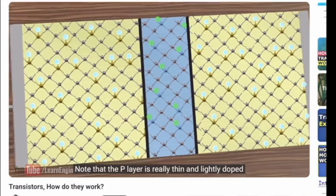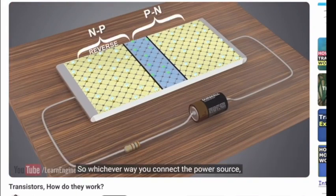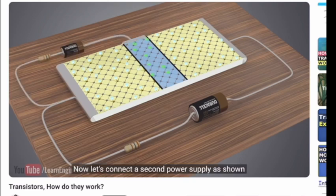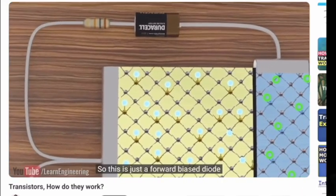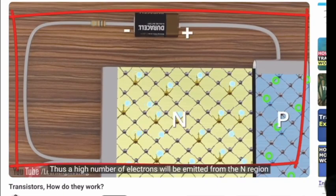So now what we're doing is we're creating 3 layers. So you have an N, P, and N type. So you have diodes, a PN that's reversed, and then you also have an NP that is the normal flow. And so this is the transistor itself. It's a BJT transistor. And in the BJT transistor, if you put on voltage between that base and emitter, you get a forward biased diode there. And so it flows just like the normal one.